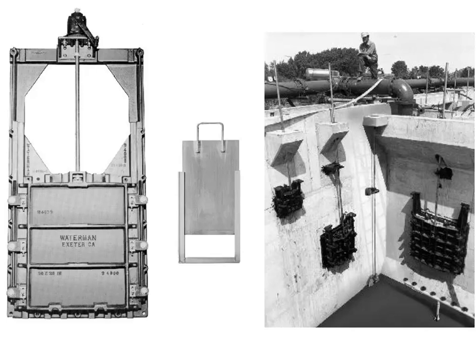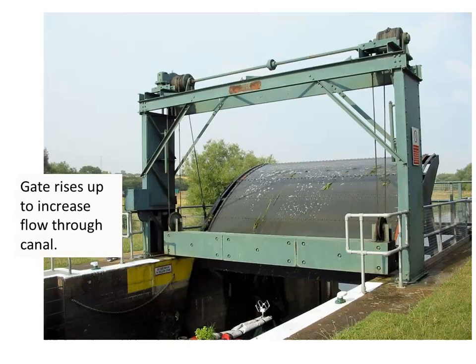It may not be the case any longer, but this is a flow equalization basin at a wastewater treatment plant. And you can see that there are a number of different gates here at different elevations. And the purpose for that is that depending on how much water is inside of the wet well, they want to be able to direct water to different places. There are other bypasses, and in fact, not pictured there is a sort of an overflow spillway where they could discharge wastewater directly to a stream if the water levels got too high. So gates are used to control flow rather than measure flow.